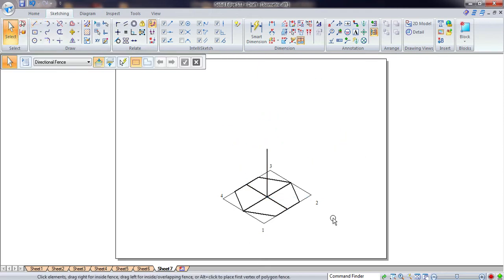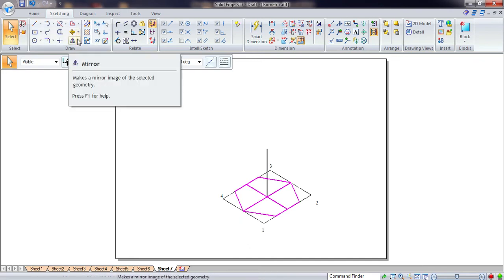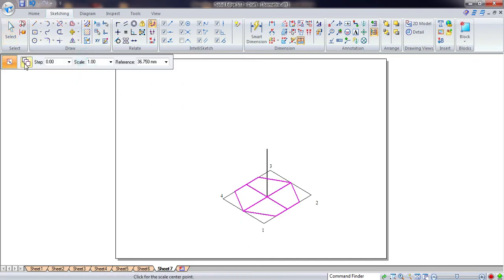In the computer you have an option called the scale command. Now select this bottom face of the hexagon, or select the six lines together with these midpoint lines. Go for scale, switch on the copy, and here the top dimension 18 divided by the bottom dimension 30.